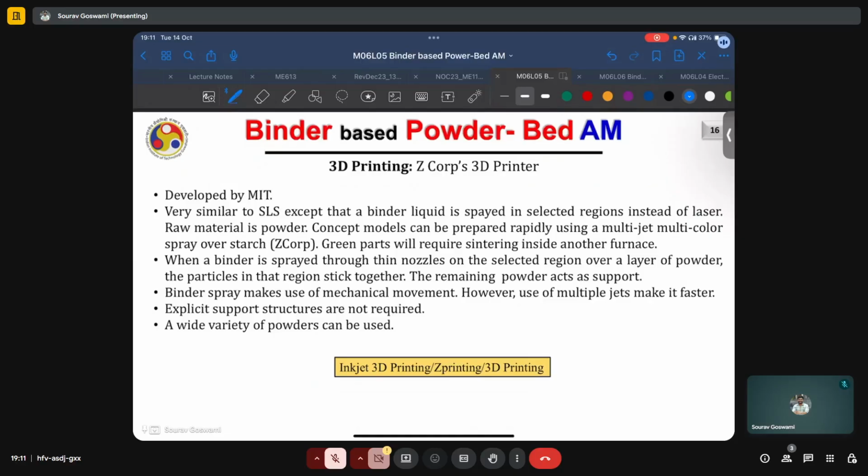In the case of selective laser melting, we still required support structures. However, the purpose was quite counterintuitive: rather than to prevent the overhanging features from falling down, the reason in this case was to prevent them from warping upwards and colliding with the roller or other machine parts and damaging them. In this case, since the material is not experiencing such high temperatures and thermal gradients, the risk of warpage is almost non-existent, and so the need for support structures is almost eliminated altogether. They may still be required for some very critical sections or very large overhangs, but typically their need will be minimal.